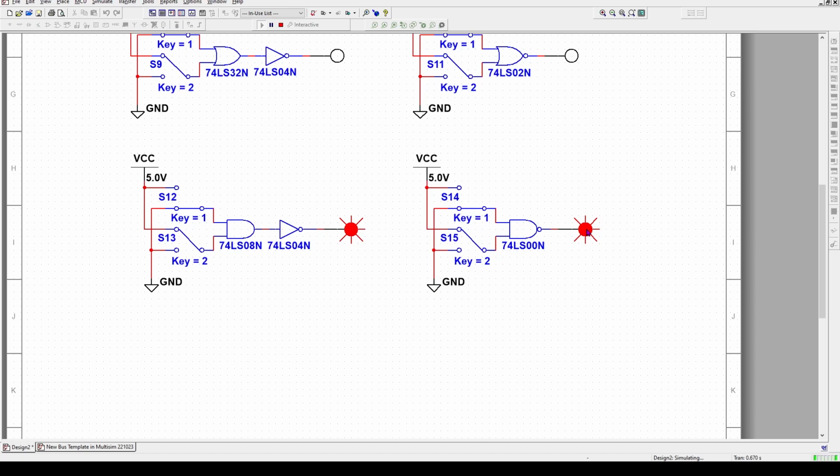Flipping it over so it's a 1 times 0, and of course that's going to be the same answer. 1 times 0 is a 0 flipped over to be a 1. And then 1 times 1 is 1, and that's flipped over to be a 0. And so we just proved that the expanded AND and NOT does the same thing as the NAND gate. Well, so far, so fun.